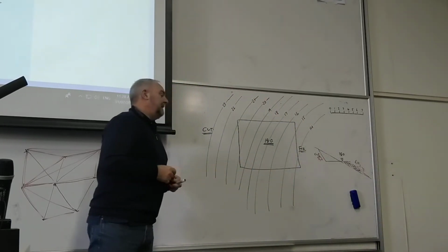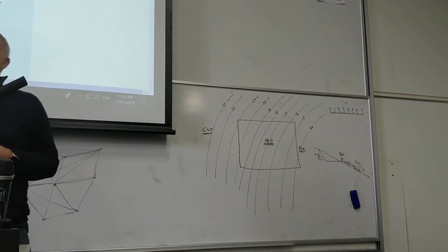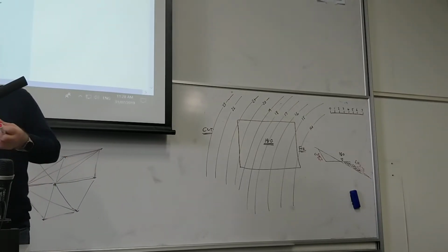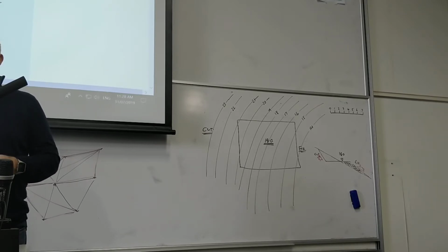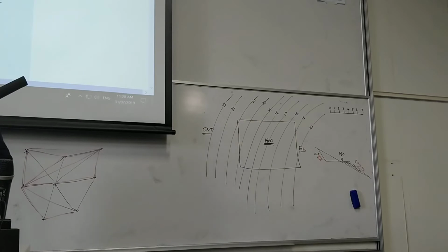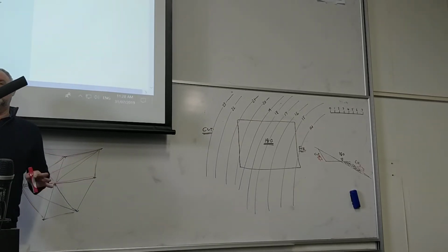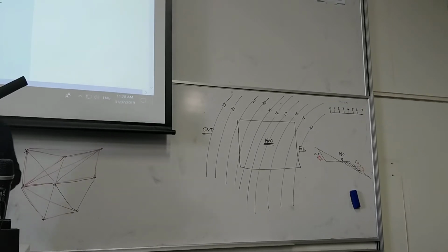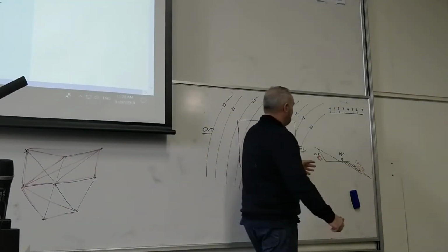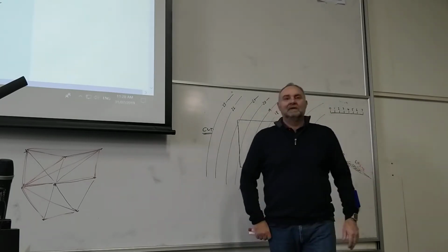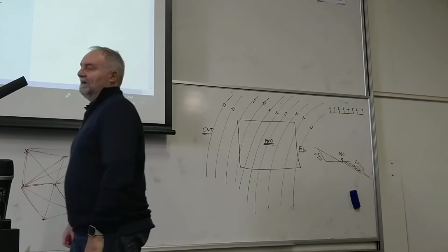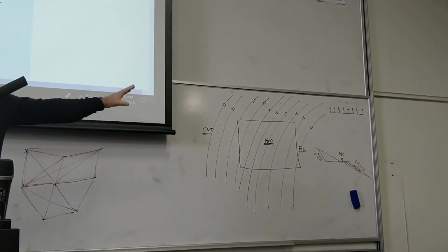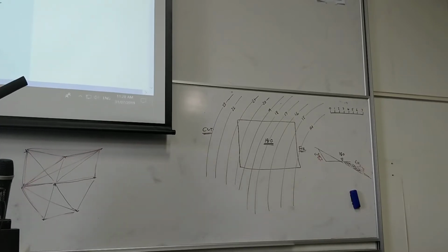Okay? And I know that a lot of students have not been brought up with things like 1-to-1 and 2-to-1. They've been brought up with angles, and a lot of students end up going, that's an angle of X because of Pythagoras something or other. Well, we're not going to be doing that in my class, so I'm going to play over your head a little bit. We're using grades. Now, interestingly enough, that is actually a very common grade to use in Auckland soils, Auckland clays. It's not always perfectly 1-to-1 or 2-to-1, but it's pretty close. So I'm trying to make the assignment close to what you might be using in real life.